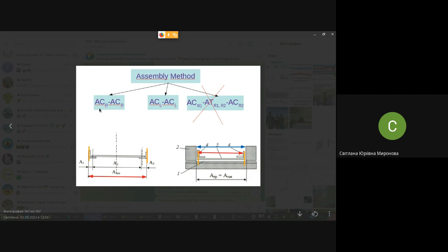If we are not able to follow the principle of locating by mating only assembly bases, real design basis, in this case we do a trick: we change the basis proposed by the designer to some other basis, processing basis or technological basis, but they anyway really exist.